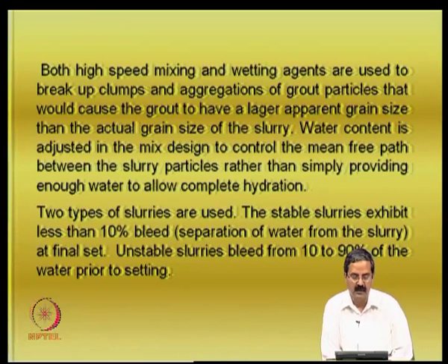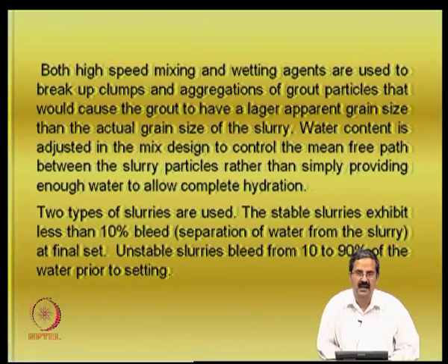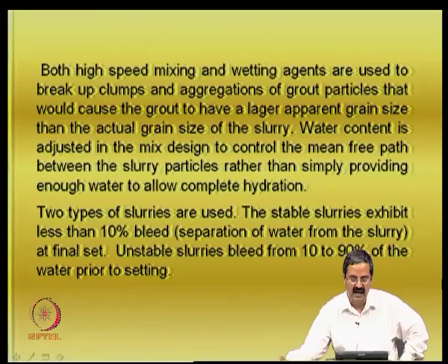Another important thing is that the water content should be sufficient so that water is available everywhere in the grout, rather than simply having enough water for hydration. The objective is to see that the water is well distributed in the complete grout.